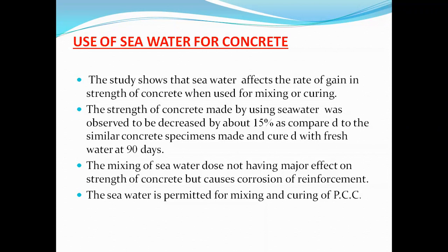Next, the mixing of seawater does not have a major effect on the strength of the concrete but causes corrosion of the reinforcement. That is, there is a decrease in strength of about 15%, but the larger effect of seawater is that it causes corrosion of the reinforcement.